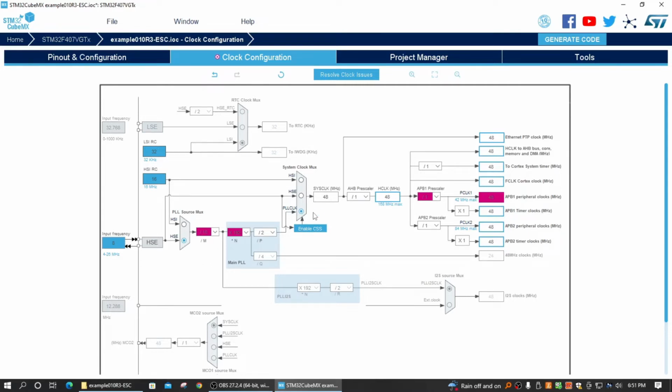We're trying to get the maximum out of this clock. So this was a divide by 4. And this is 168. It's a 168 megahertz processor, so that's the fastest this processor could run. And so we got that 168. We want this to be divided by 4, and this to be divided by 2. So I believe everything is good there now in our clock setup.